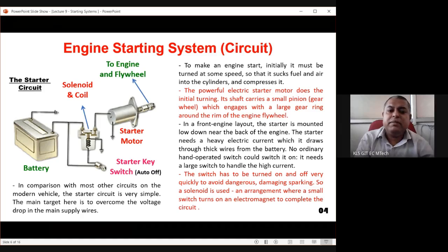Okay, so the coil inside the solenoid gets energized, and as soon as this coil gets energized, this thing comes down, or these two metal plates are actually pulled up. So now this path is actually shorted, so current goes directly from the battery through this solenoid to the motor. So these are the two things that happen initially.